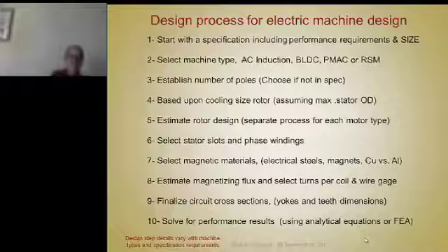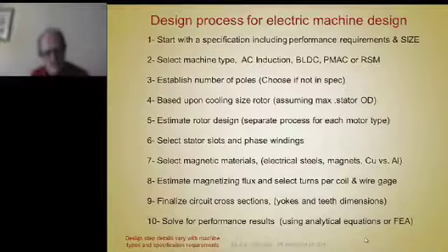So that's a fractional slot winding, but that's a winding whereas the coil is wrapped around a single tooth, so that the amount of copper in the end turns is no different than the cross section of what's in the slot. If you span multiple slots and you got a lot more copper there to mash down, it's going to stick out farther past the ends. It's harder to cool that as well. It's harder to cool the multiple slot winding. So manufacturing has a lot to do with it. If you want a real high slot fill and you want to automate the winding, then you almost have to use a winding where the coils are around individual teeth.